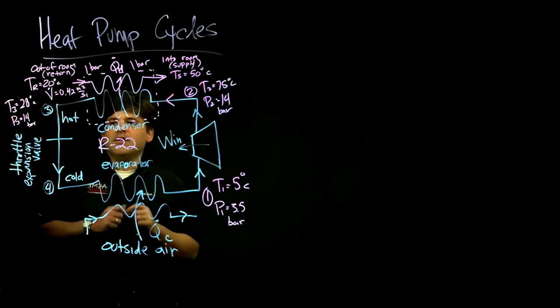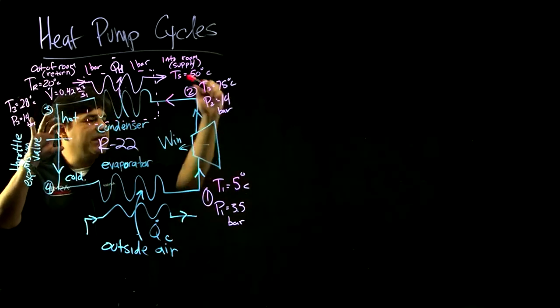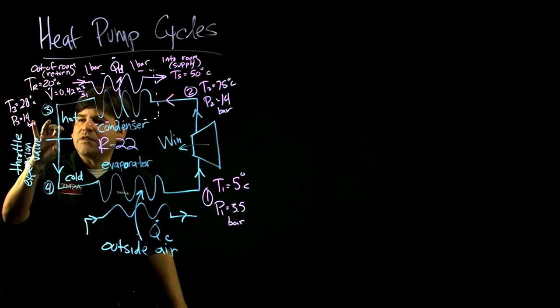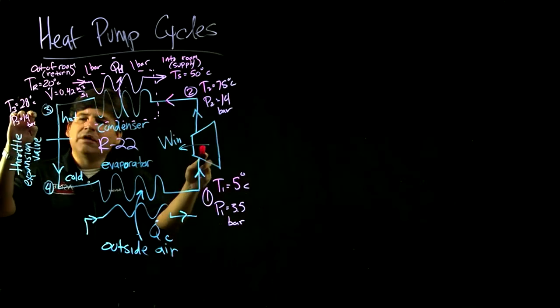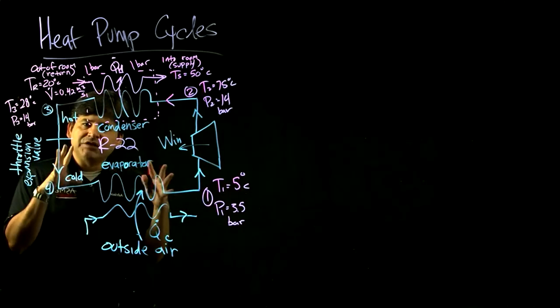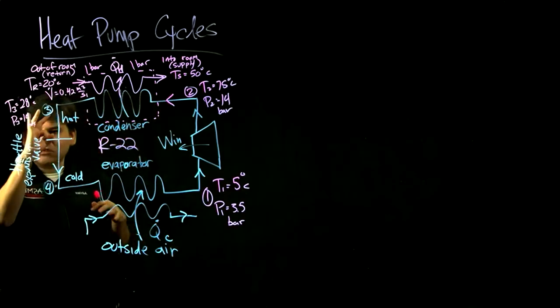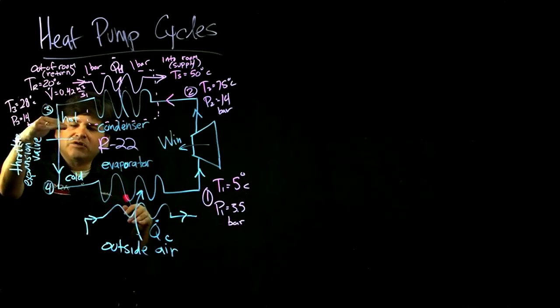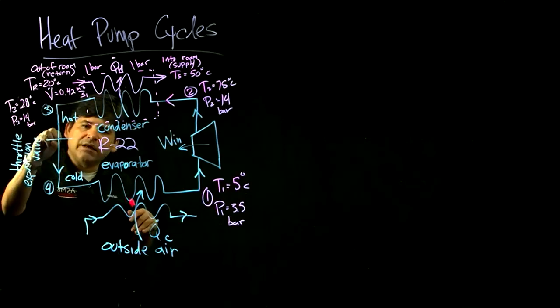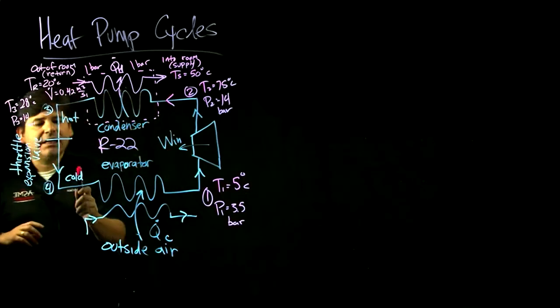Okay? Then the special part of these reverse heat engines is that if you pumped it up to this high pressure and you expose it to some expansion valve, just some quick nozzle, where it's high pressure on one side, low pressure on the other side, the response of this refrigerant molecule is it's going to get to a cold temperature.